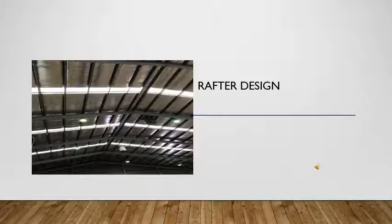Rafters are sloped beams that run from the roof ridges to the eaves. They provide the support for the external roofing material. Beam-column connections are pinned joints, so we assume the rafters to be simply supported. Also, we assume that the roof loading will be transferred from purlins to rafters as uniformly distributed loads. The rafter material in the picture is steel, which has a clear span distance.